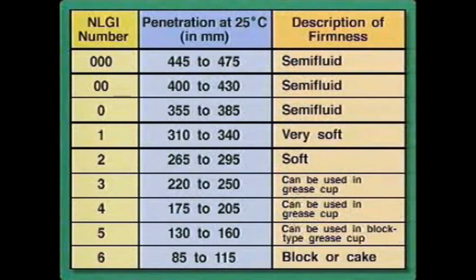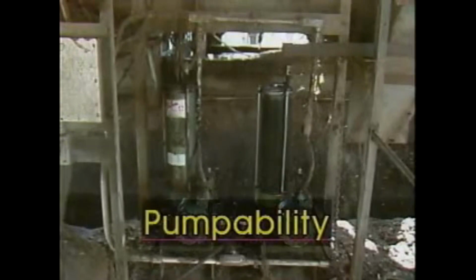If a grease must be pumped through a centralized greasing system, the grease's pumpability should be considered. Pumpability is a measure of how easily a grease can be moved or pumped through a centralized greasing system without clogging the pipes or the components in the system.